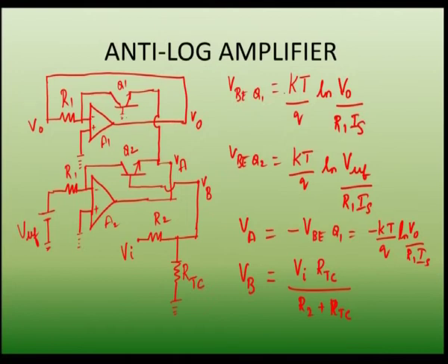So, we are removing this negative sign. Similarly for the transistor Q2, VBE is from base to emitter, but always we will calculate the output voltage from this terminal, the output of A1. In the logarithmic amplifier, when you recall, the output is connected to the emitter terminal of the transistor. So, we will be reversing the voltage, that is why the negative sign is neglected here, or negative into negative you will be getting positive sign.